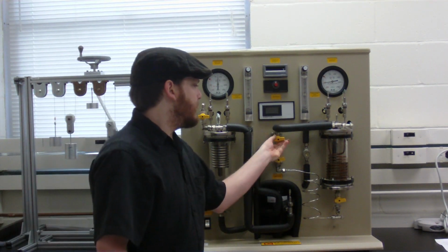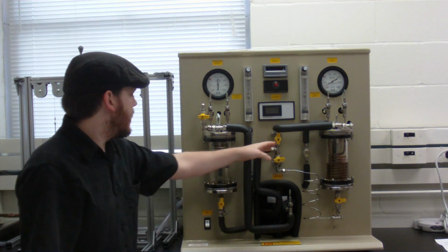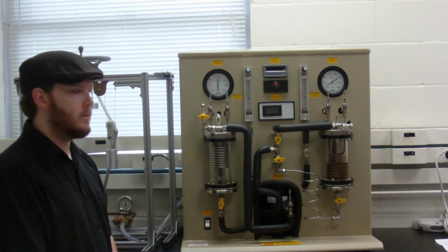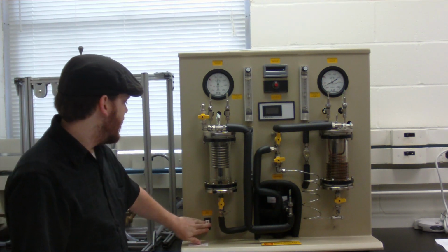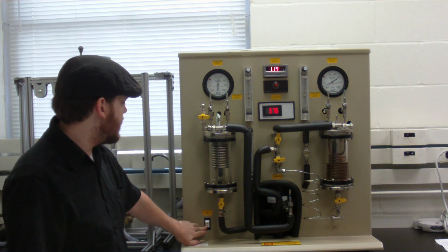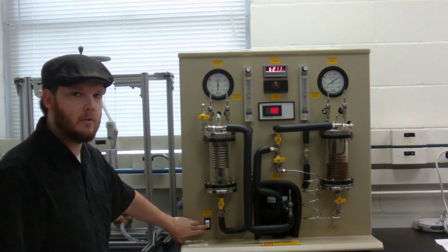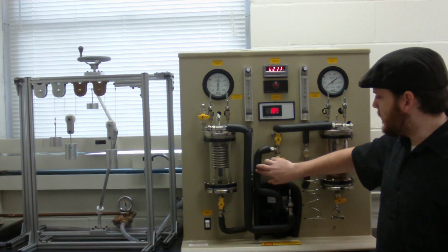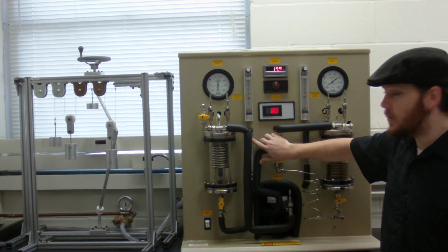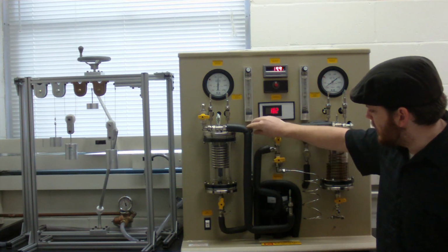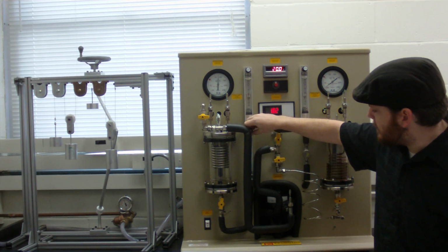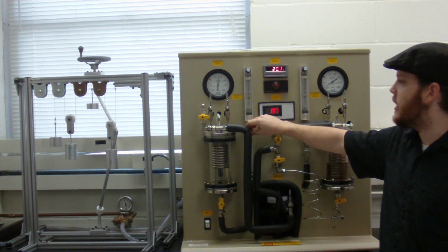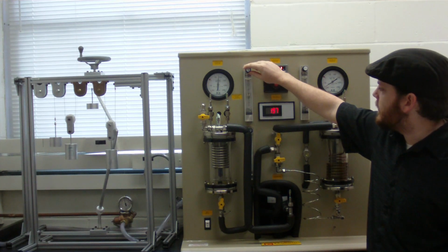This is marked in the lab write-up. Make sure you turn the correct two valves. The other ones may vent coolant out into the atmosphere. Once those are turned on, you can switch your main unit on with this switch down here. Now the refrigerant level may be a little difficult to see, but it's right here. You can turn the dial to get the piston to rise to the flow meter settings as described in the write-up. Same goes for the water for each one.